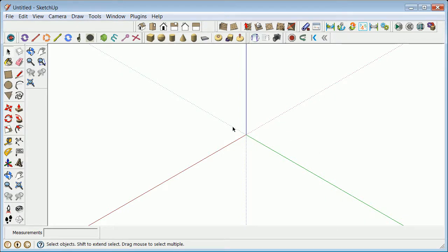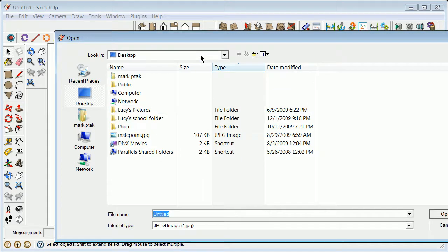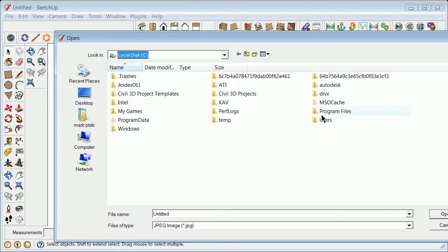So what we've done, and originally, if you remember, we drafted flat. We used the B poly command to make regions. We used extrude to make those regions into solids. And now our hope is that when we do file import, we can go ahead and import, if we remembered where we put it, which is not always so easy.